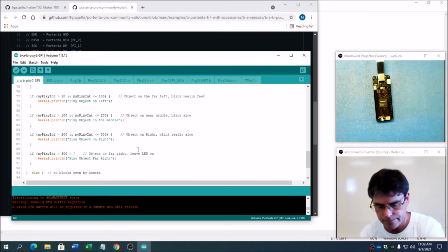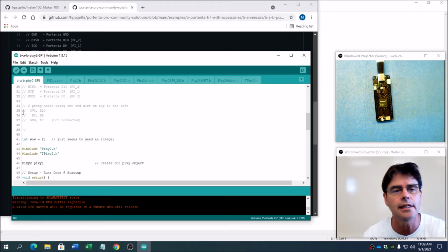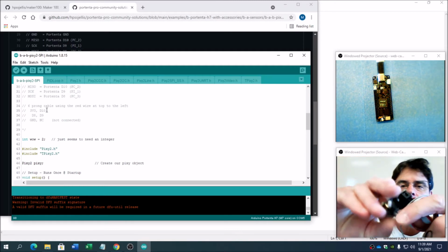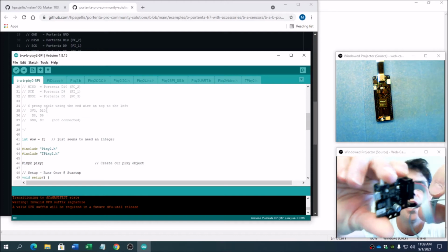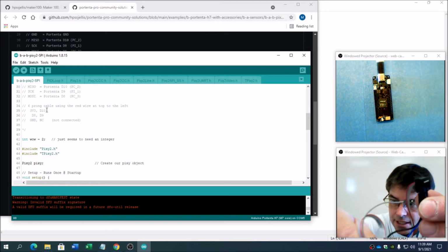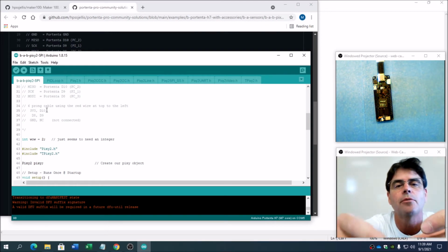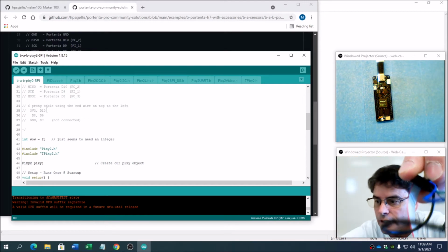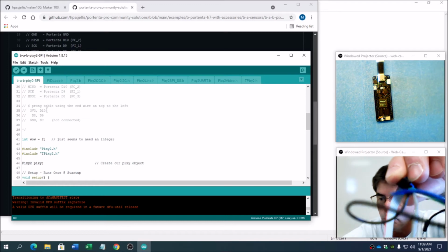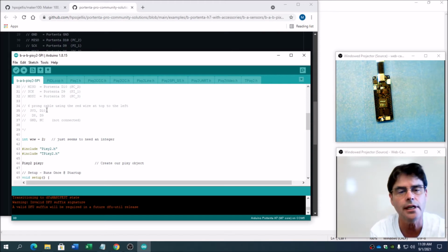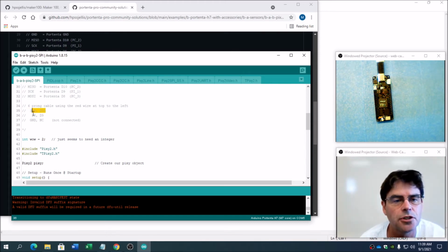So next thing, here it talks about the 6-prong cable. And let's get this 6-prong cable here. There's your Pixie on the back. There are two connection techniques. One is, well, it's a 10-prong here, but on this side, it's a 6-prong. And what we're doing here with the connections is we're looking at it like that. Yeah. How can I show that? See the red wire? The red part of the ribbon is on the top, and you're looking at the wires. And so pretty easy, we just read them off because they're in groups of 2 here.